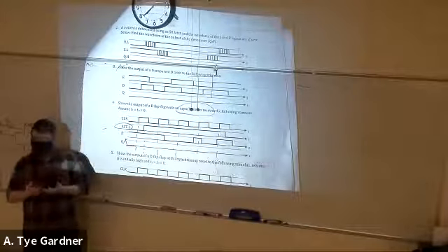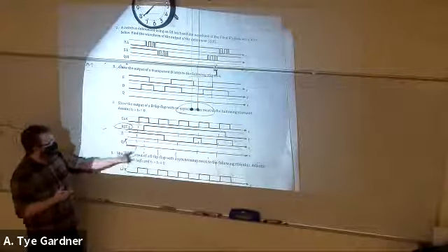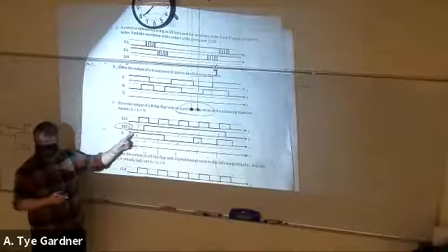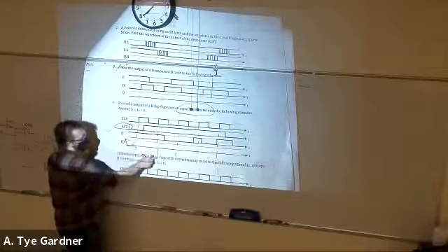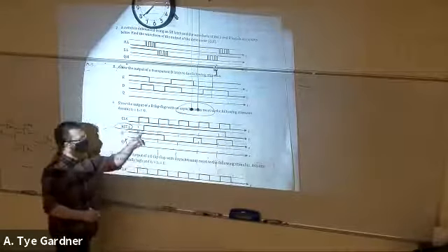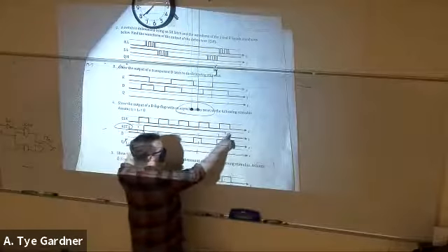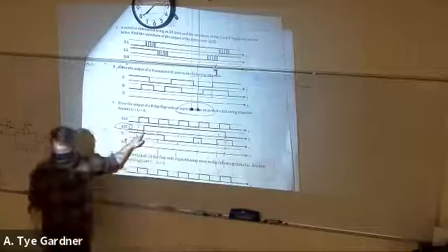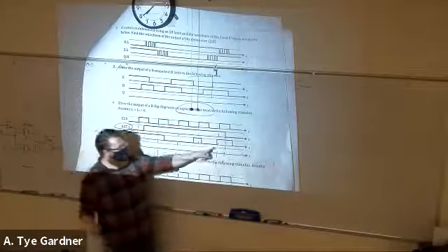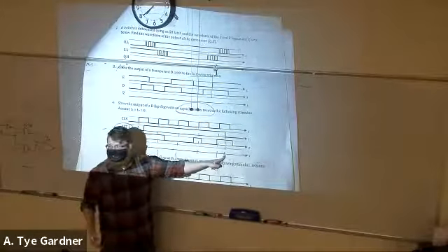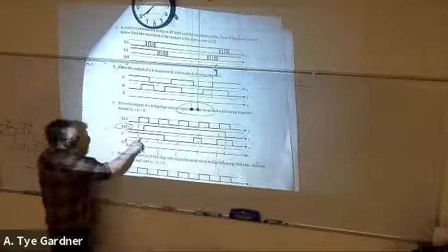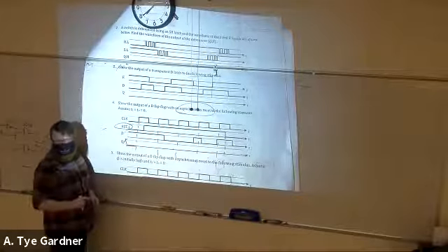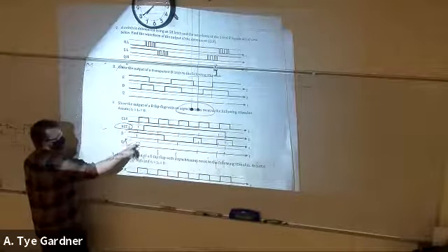It's not going to change there because it's not a rising edge, and we're not going into reset. So it's not going to change from what it was before. This one is don't change. That was the biggest mistake I saw when I went around. Whereas here, when this drops, we are transitioning into a reset. So if we were a 1, this would become a 0. Whereas here, whether I'm a 1 or 0, I'm going to stay 1 or 0 in the same spot. That was the only gap.